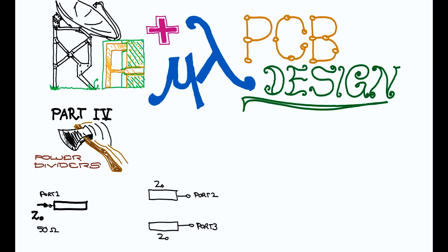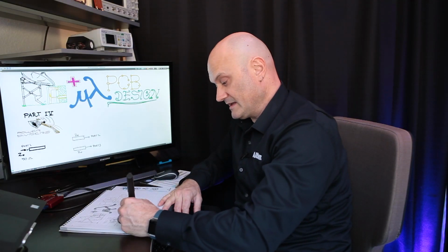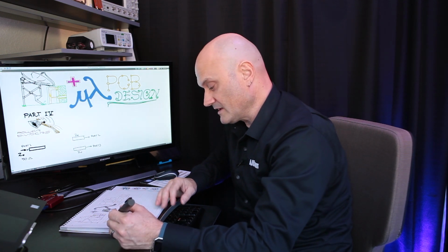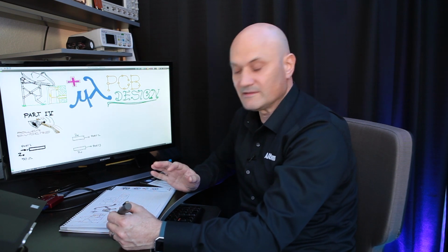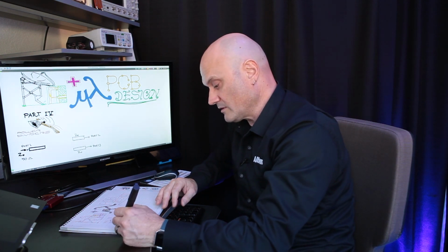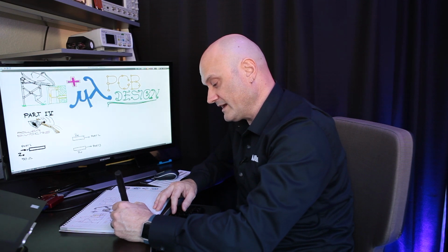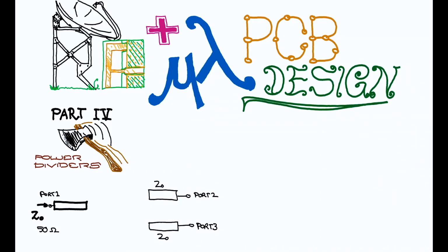Now what do we do? We can't just connect two 50 ohm lines in parallel to this 50 ohm line, because then we'd have 25 ohms effective and we'd get reflections that wouldn't be matched. The system wouldn't be matched. So what we want to do where we divide is have 200 ohm segments, so we can split that off effectively into two 100 ohm lines in parallel at that point.